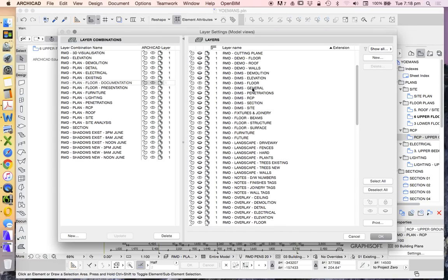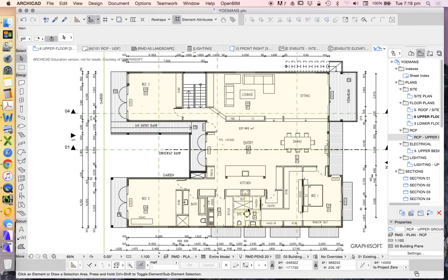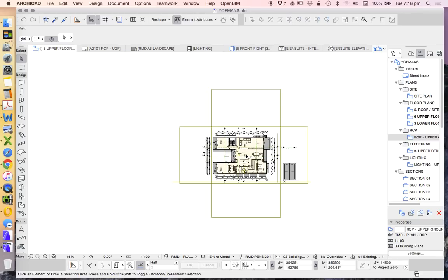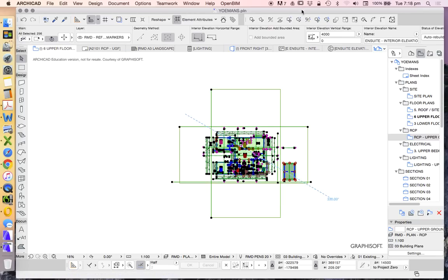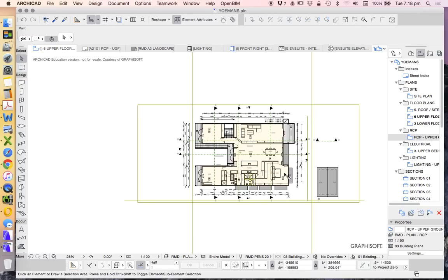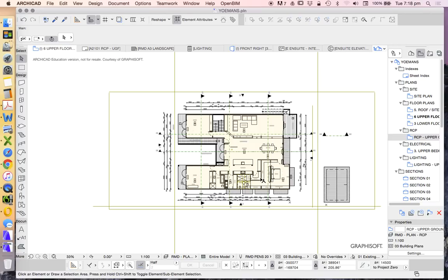Of course, I'll have the same sort of setup for dimensions because I want to do the same sort of idea with dimensions. We don't copy and paste. So when you've used AutoCAD, maybe you've copy, drag a copy, and you've got multiple drawings on a page. We don't do that in Archicad. It's really bad management, makes your file size big, and it means you're duplicating errors. So if you need to fix things, you need to fix them more than once. We don't do that in Archicad.